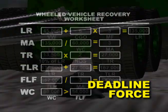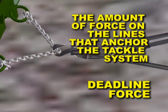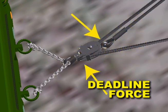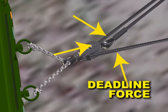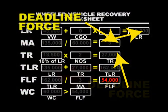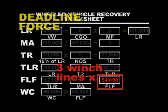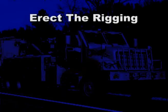Deadline force is the amount of force on the lines that anchor the tackle system. To calculate our deadline force, we must count the number of winch lines supporting the deadline and multiply by the fall line force. Now that all the calculations are done and we are aware of how we must rig our system, we can begin the 6th step of recovery, which is erect the rigging.